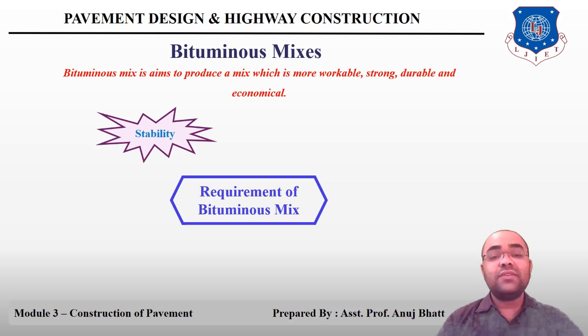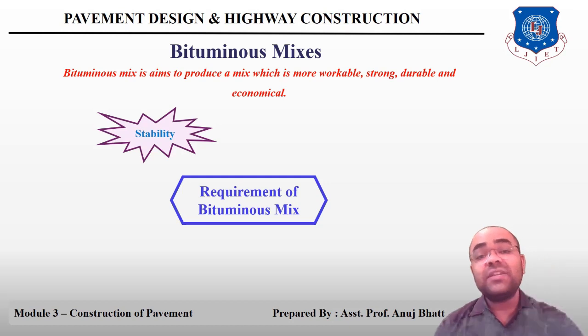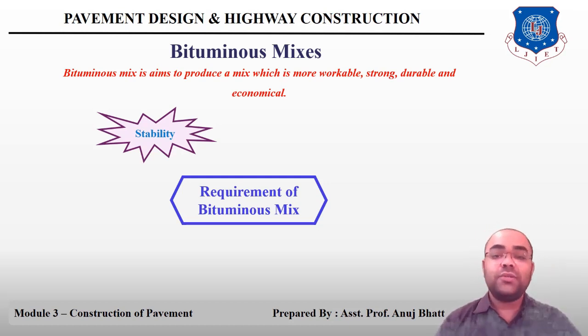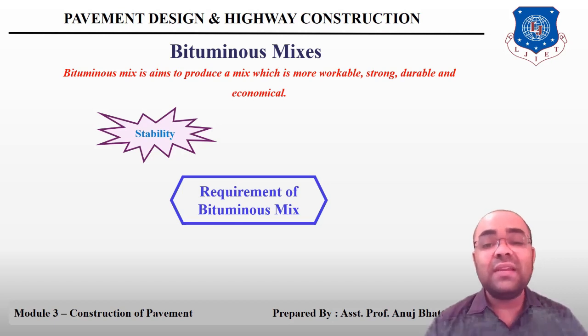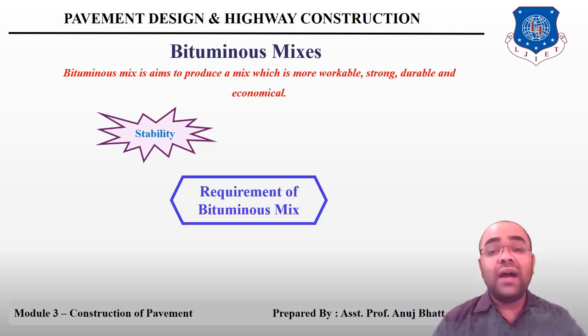Shoving is a transverse rigid deformation which occurs at areas subjected to severe acceleration, while grooving is longitudinal ridging due to channelization of the traffic. The stability depends on the interparticle friction primarily of aggregates and the cohesion offered by the bitumen.